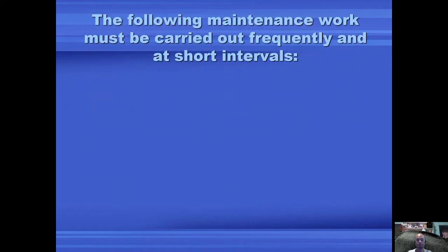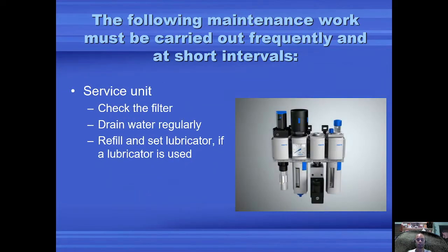Okay, the following maintenance work must be carried out frequently at short intervals. First, always check the filter. Usually there are transparent glasses so you can see the filter and check the water, or if not, drain water regularly, every duty.